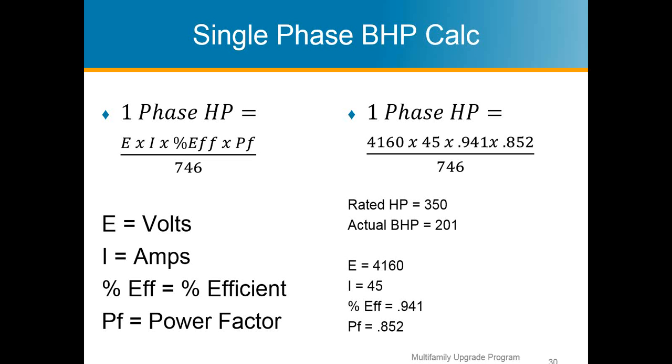But yeah, if you have those high-rise buildings with central garage exhausts that are on a VFD, or on carbon monoxide sensors, where it's going to power on and operate for certain parts per million, and it's going to operate for 20 minutes until that's diluted, these are all really fun hand calcs you get to do on the side if you're going to get into the weeds of calibrating it and figuring that energy consumption out.